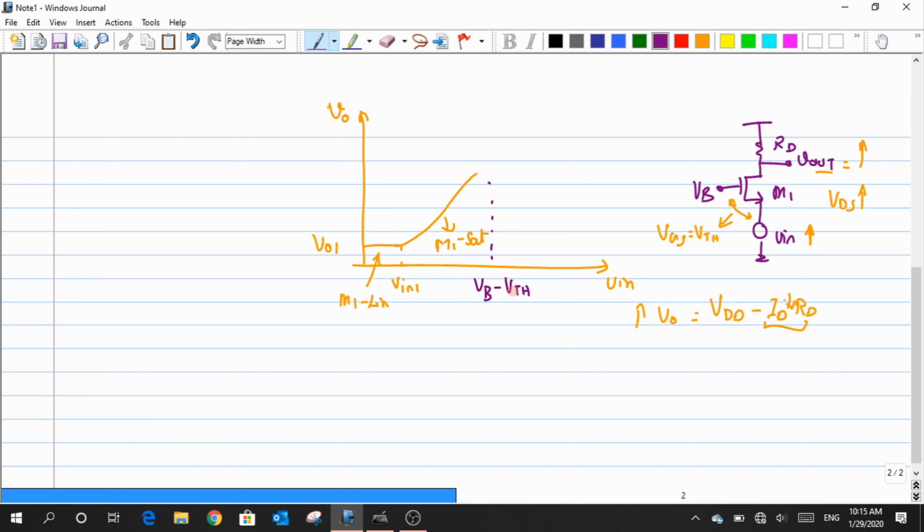At that particular point, my transistor M1 gets into cutoff. So in that case, what would be the value I would get out of the circuit? It will be equal to VDD. I hope there is no doubt in it, because the current becomes 0 in that case. So the Vout would then be strictly equal to VDD itself. Clear? So in this case, I have this M1 in the cutoff regime.